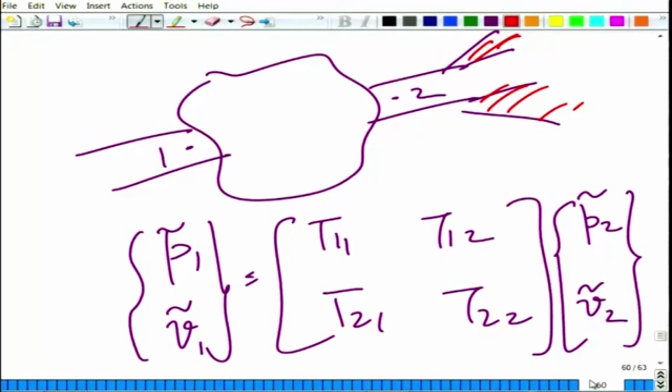And once we know the generalized expression, which should be straightforward to derive, we can use the transfer matrix for an extended inlet and outlet element and plug in all the parameters and obtain the rather tedious expression for transmission loss, and then possibly draw some conclusions.